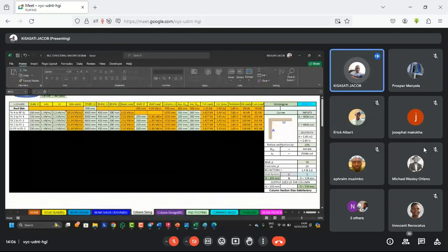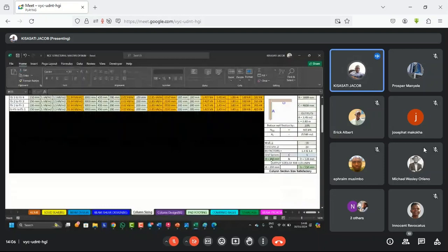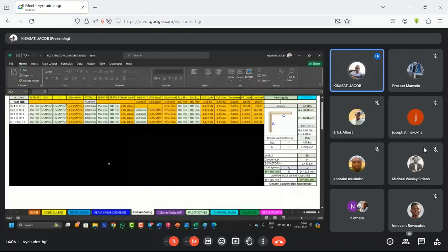This one for today, because we are not going to print, but we can print this after that. Now, the assumed value: if we assume 200 by 200 for this structure, then the other side will be 128. As you can see, for this building, we can just use a 200 by 200 column, because the figure is small. So 200 and 200 will work.